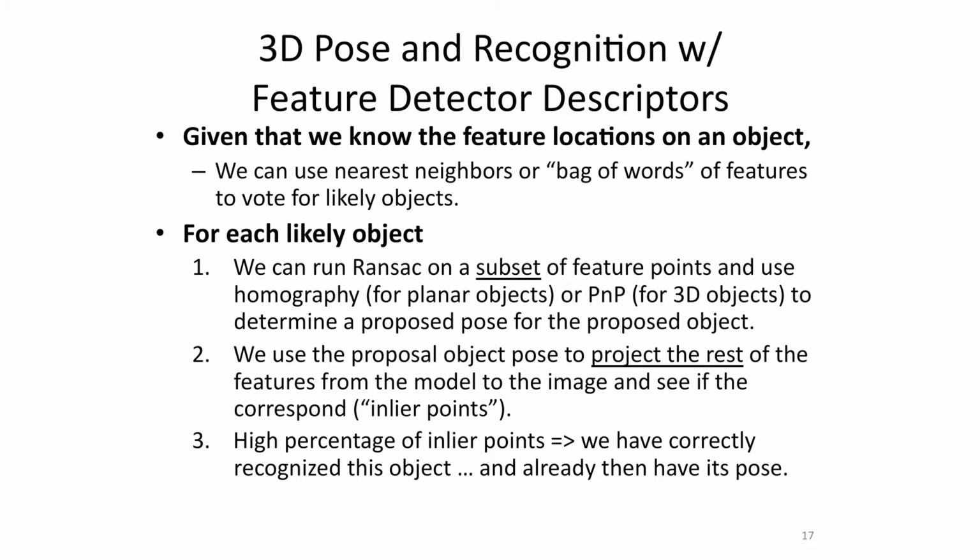If they match up, then pretty surely you've got your object and you've got your pose. And so you use a routine called RANSAC to do this random sample consensus of taking a subset and then fitting the whole, and to maximize inliers, throw out outliers, and so there's a whole technique based on that of using key points and determining poses of objects.